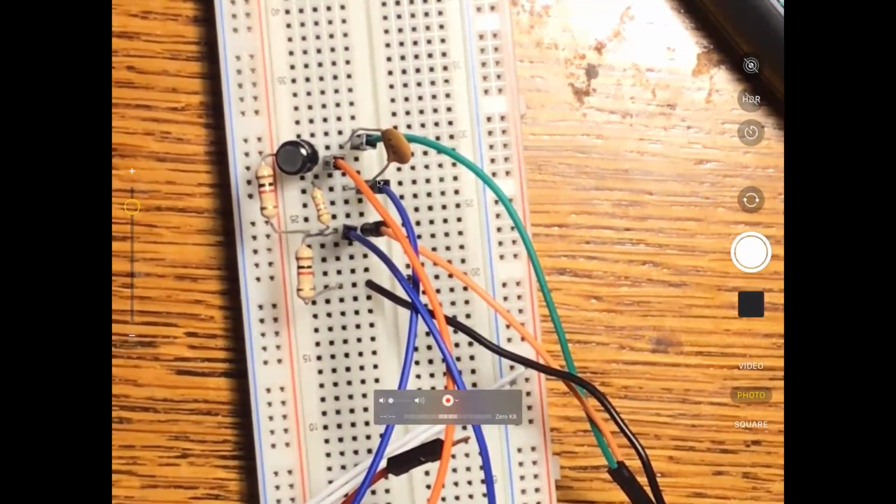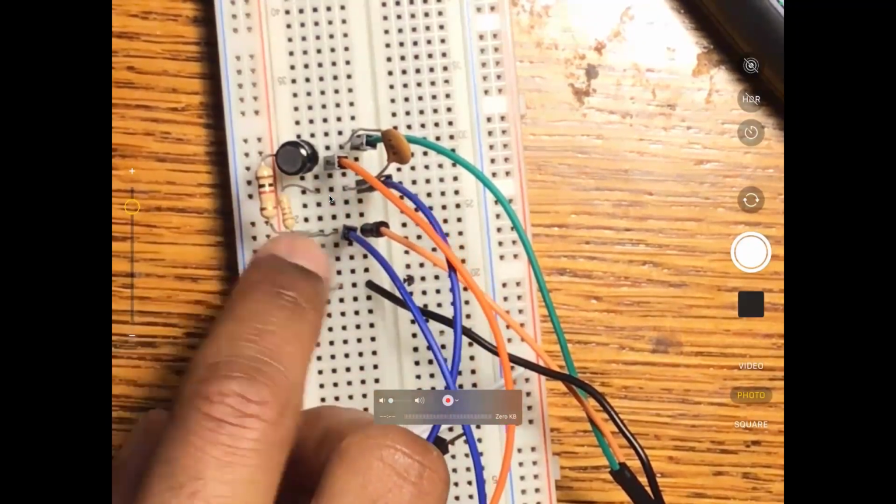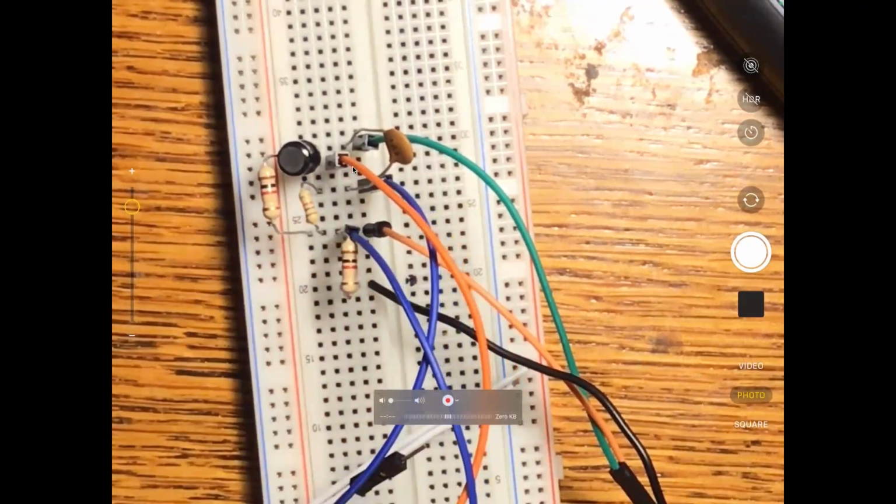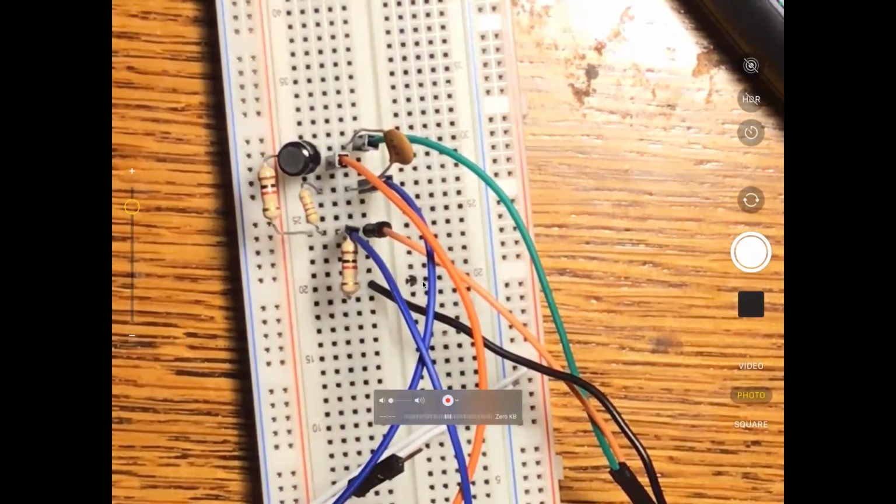supply branch. And then channel 1 is measuring that voltage drop across. Okay, channel 1 is measuring the voltage drop across that resistor in that inductive branch. Channel 2 is measuring the resistor in the capacitive branch.